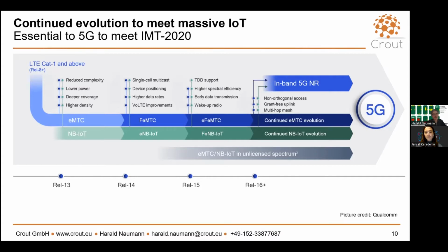But if you make a development and would like to sell it in a big region, then you will end up with combined devices, because in the States, LTE-M is much better available than narrowband IoT. And if you would like to sell to China, there is no LTE-M, so you have to use narrowband IoT. Okay, so there are other concerns. The timers are the same. I have seen that other people will talk about eDRX, for example. The timers are the same; the values of the timers are different. But if you talk about something that should transmit once a day, you can do this with both technologies.